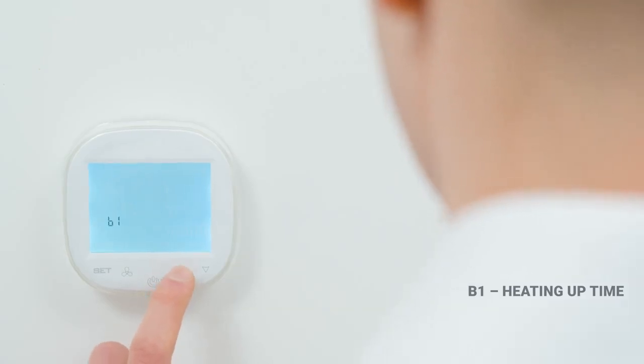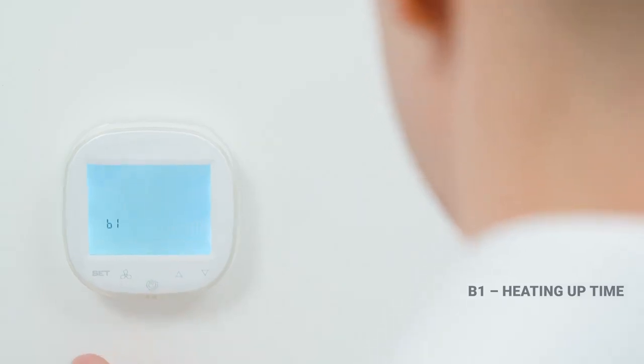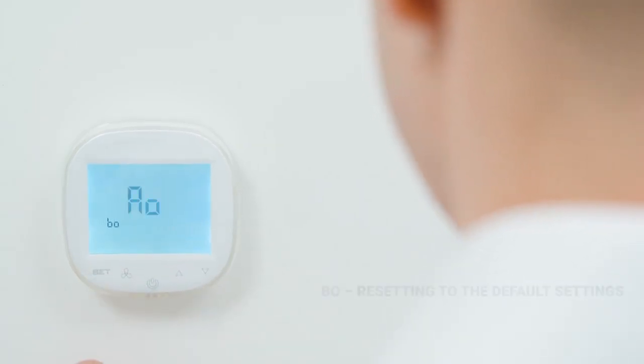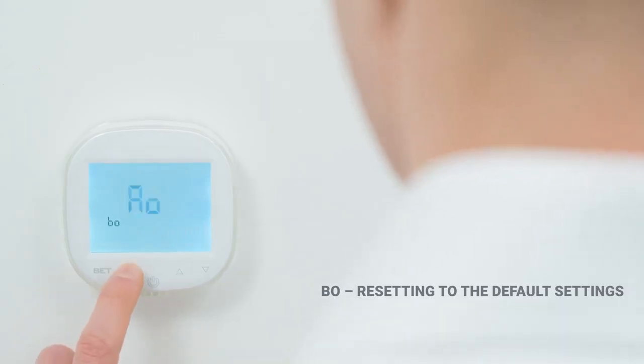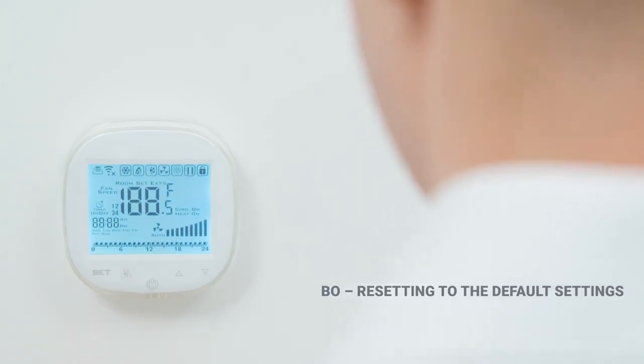Function B1 allows us to set the time for which the curtain will keep heating the room after the door is closed. We can set a value from 0 to 90 seconds. Function B0: this is to restore the default settings. The settings are restored by holding down the fan button.